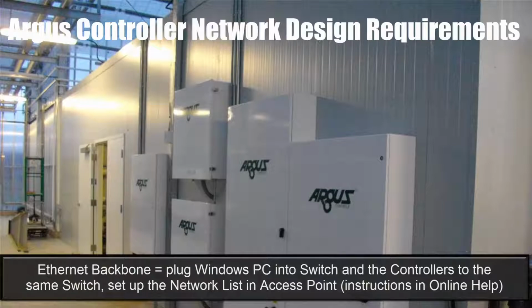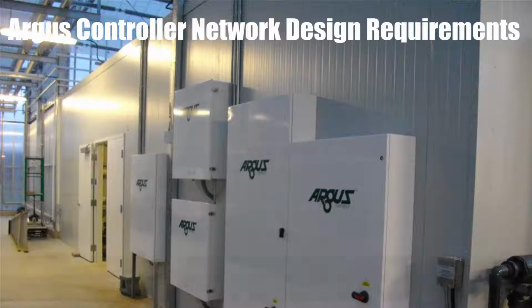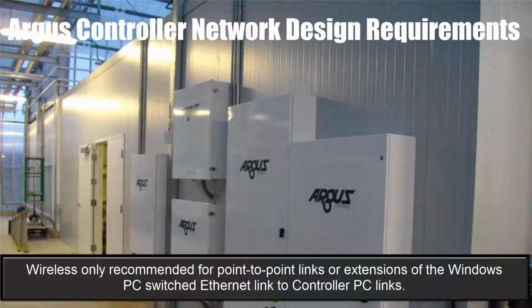For the Ethernet backbone setup, simply plug in the Windows PC to the switch and the controllers to the same switch. Set up the network list in the access point as per the instructions in the online help and you're finished. Wireless is only recommended and supported for point-to-point links or extensions of the Windows PC switched Ethernet link to controller PC links.